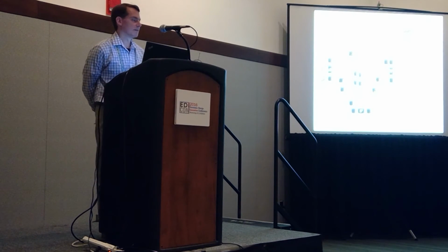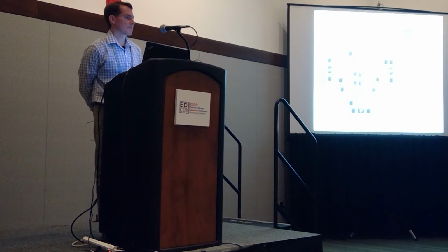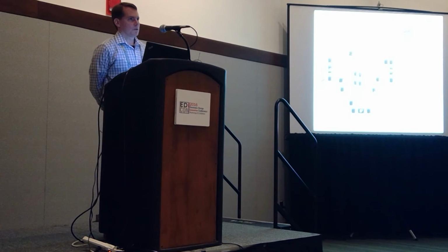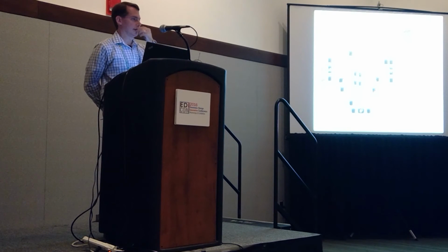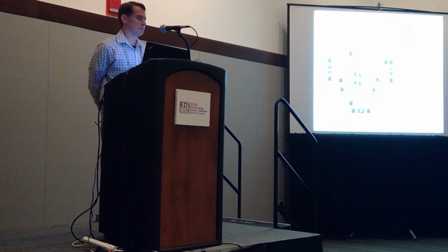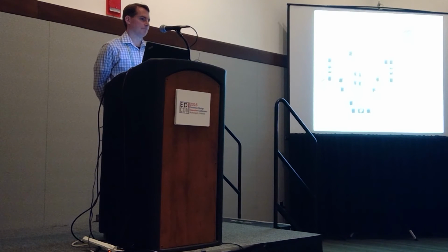Would there be an advantage if you use a square wave for the LO instead of a sine wave? The question is the shape of the LO waveform, square versus sine. Again, in theory, there could be. But what we find in this double balanced diode mixer, especially because we have a ring of diodes, is that it clips the LO waveform and you generate a quasi-square wave in that ring. So going to a square wave LO here doesn't buy you much. On the three-terminal FET devices, it can. We've seen a little bit of that.